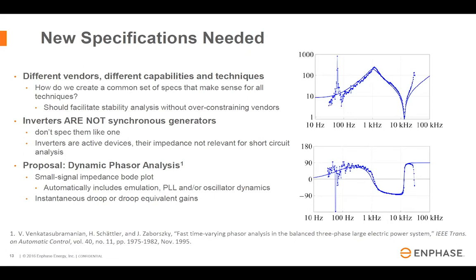So the Bode plot would include the dynamics of your EMI filter, it would include your controller, it would include your PLL, all in one little datasheet item that can be used for a variety of different designs as well as a variety of different analysis techniques. So you can imagine that you could use this for transient simulation. You can also use it for more quasi-static simulation, like dynamic phasor analysis and such.